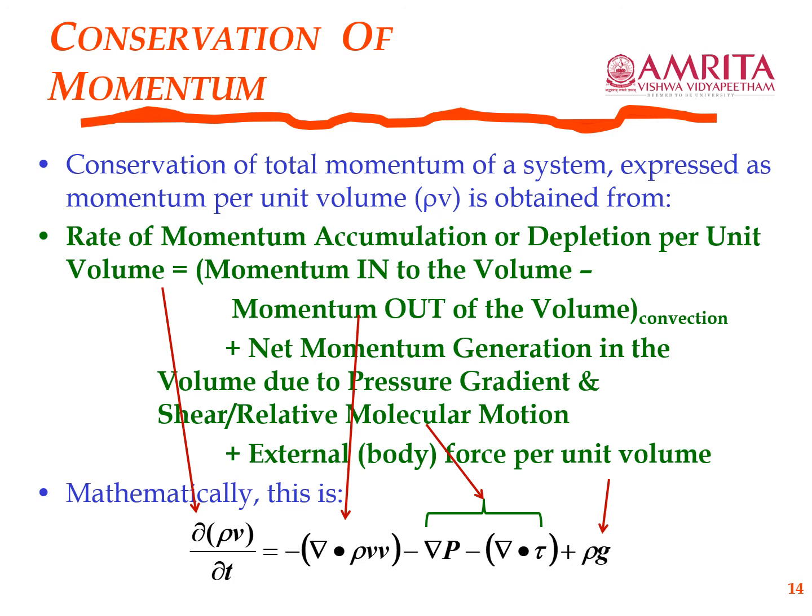That is del dot tau, which is similar to del dot q in energy, q being the energy flux, probably given by Fourier's law of conduction, and here tau may be given by Newton's law of viscosity. And in species transport, you had del dot j i, where j is given by Fick's law of diffusion. So they all have a similar structure. And then you have, of course, rho g, which is the external body force, and del p, which is the pressure gradient.